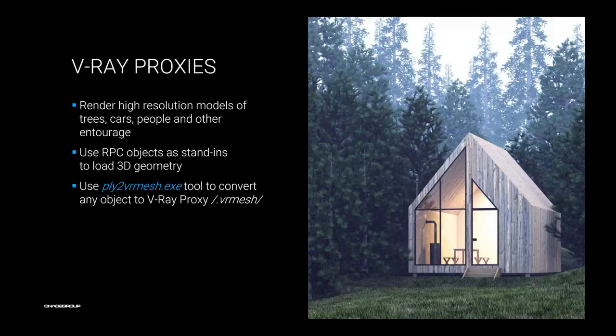Currently, we are unable to load proxies directly into Revit. For example, in V-Ray for SketchUp and V-Ray for Rhino, this is possible, and you can just place a proxy inside of the model. Revit doesn't let us do this. Therefore, you need to have RPCs in the scene because they serve as stand-ins for proxies, and at render time, they are overridden with proxies.